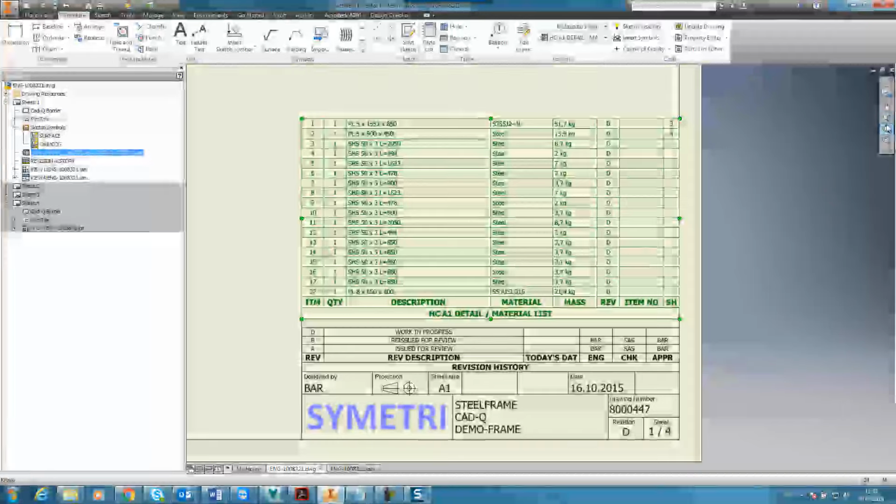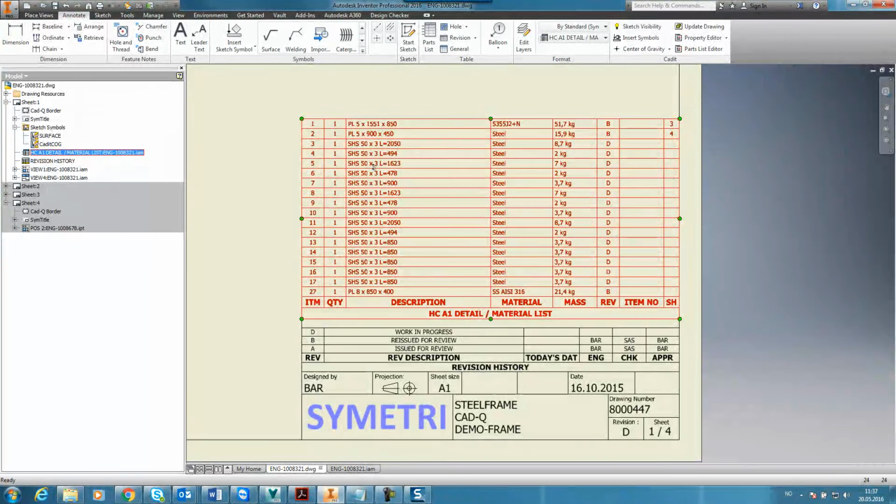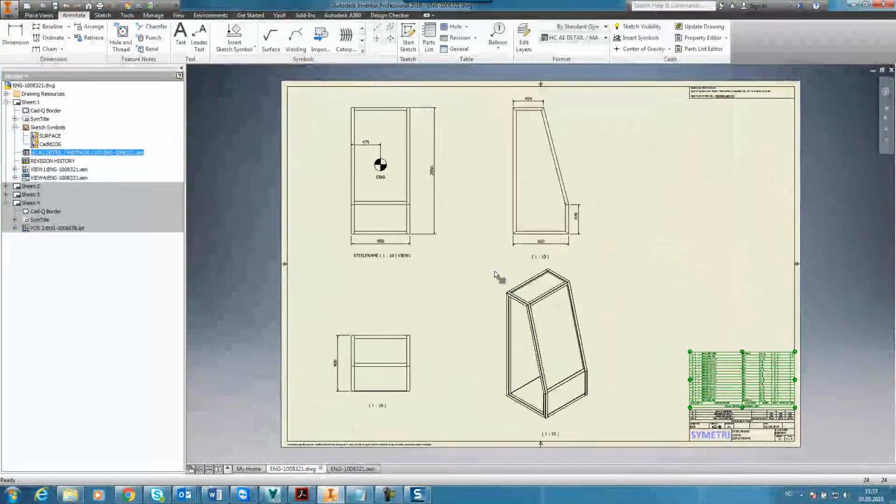But I also copy the properties from the model into the drawing properties. So I don't link this title block demo to the model, I link it to the drawing properties, because the drawing properties are derived from the model, and this is a way to enforce an item-centric workflow to avoid creating drawings of several models at a time.